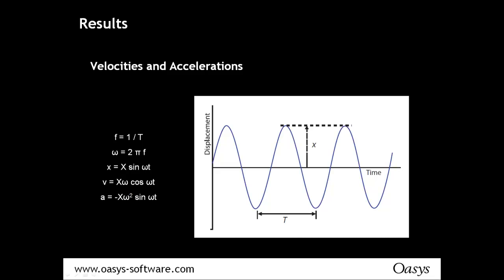The velocities might be calculated in terms of peak velocity or root mean squared, RMS, or root mean cubed on the floor, depending on the design guide and what exactly it's asking for. Likewise, accelerations might be in terms of meters per second squared, or in terms of percent g in the design guide. I'll lead you through what sort of figures you're actually looking for.